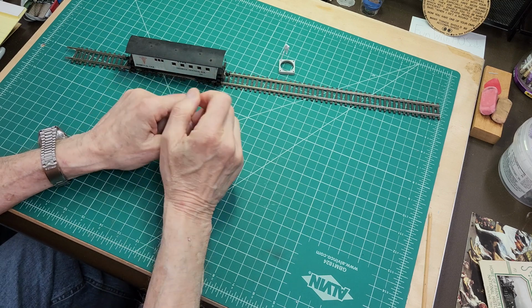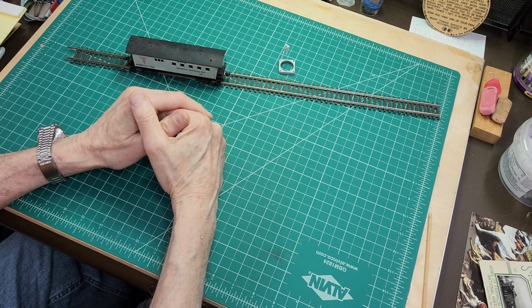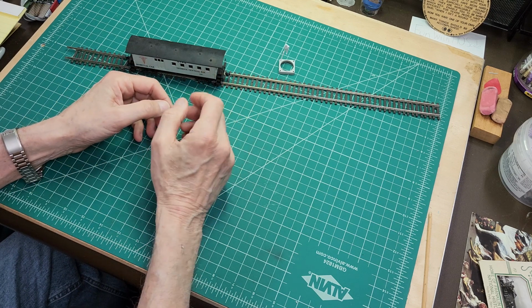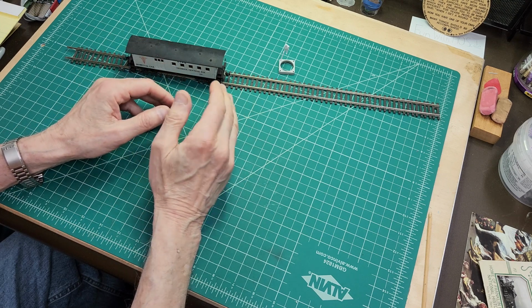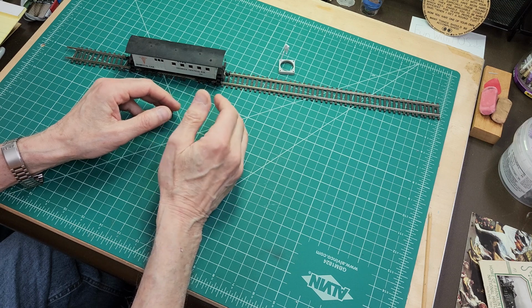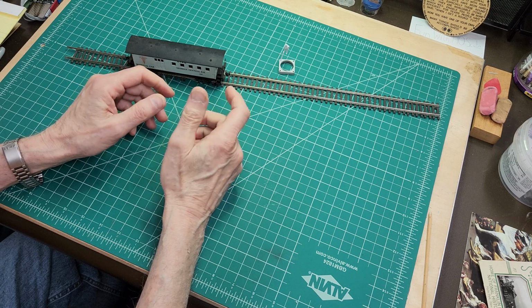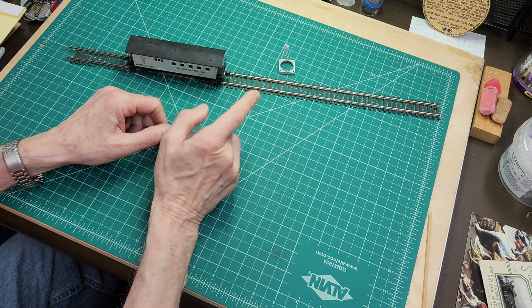As I said earlier, my driver's not working. What I explained earlier is that the host shield library detects a device attachment, and then it reads that device's configuration data. This is the way that the device defines its data ports called endpoints. I'm again showing the NCE USB interface board's USB configuration data here.